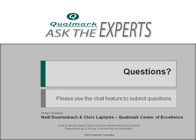Okay, thank you. And what about the pros and cons of powered versus unpowered product testing? Oh, that's right. When you talk about developing the screen, we talk some about the idea of precipitation and detection screens, where we'll run a first part unpowered and then turn the system on, reduce the stresses, and do a powered test. That's the only place where testing unpowered is acceptable in HASS as a universal opinion.